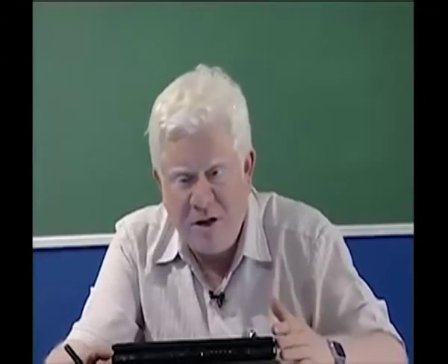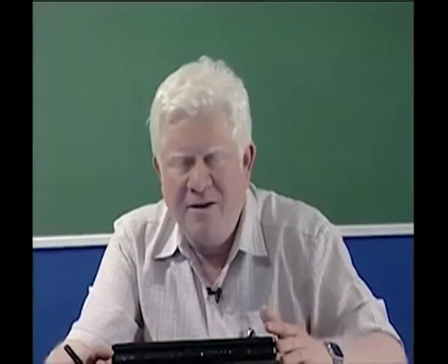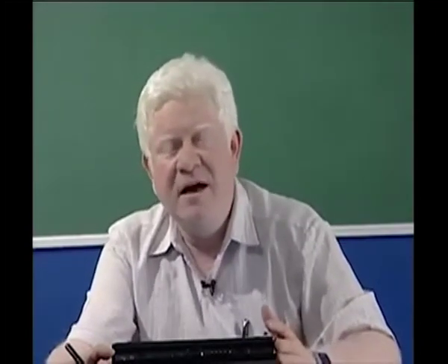Now we are asking a similar question. Can we look at a differential equation and say whether the system that is described by it is causal or not? Here again we find that what a differential equation says about the system is not exhaustive. The differential equation's description of the system is not exhaustive. It does not constrain the system to be either causal strictly or anti-causal strictly. The system is free to be either of these.